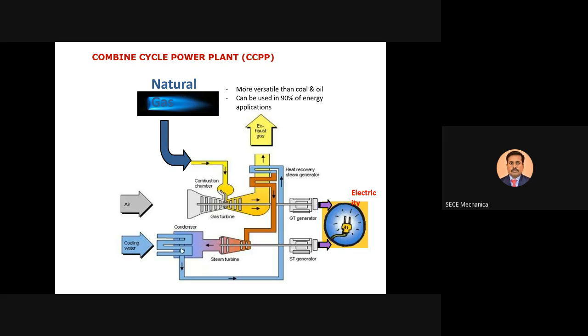From vapor to liquid state, and further it is moved to the heat recovery area, and finally the hot gas escaping from the gas turbine again touches the heat recovery zone tubes. In the tubes you have water, so the water gets heated up. So this cycle is repeated once again. In this way, we can generate two powers. One power is generated with the help of the gas turbine, and another power we can generate with the help of the steam turbine.